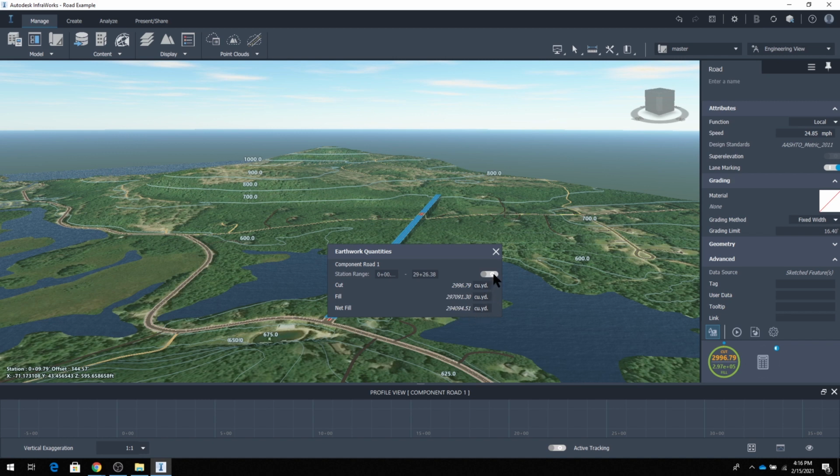Let's click on turn it on. The blue line comes on, and I can put a station in it. When you put a station in, it says station 4+00. I did this, it took me a while to get this right. So if I want to put station 2, that's 200. Each station is 100 feet. So I'm going to type in here, come up here, type in 200, hit enter. That makes it station 2.